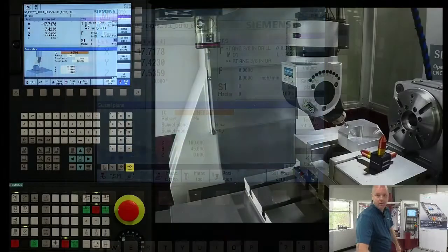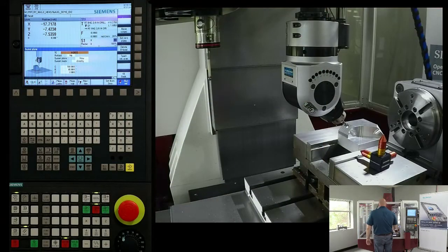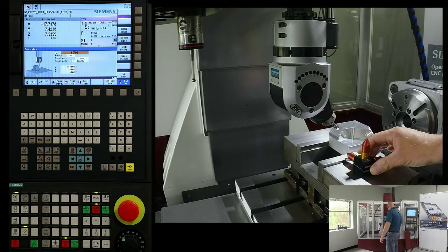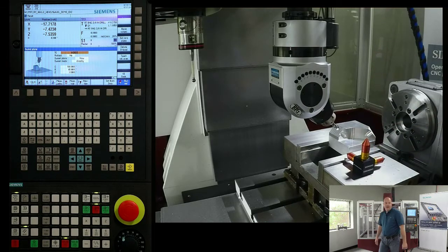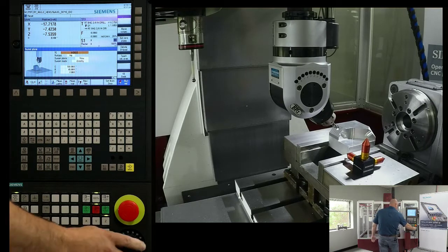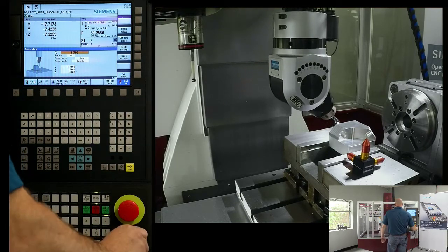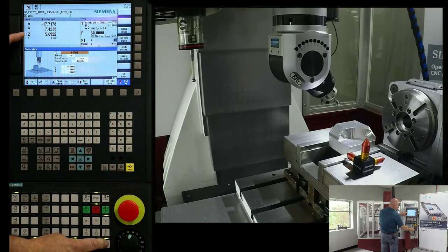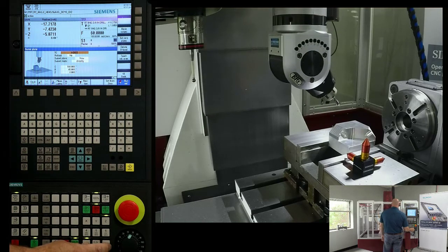So here you see an interior shot of my machine tool. Normally our coordinate system, like you see on my little cube here, is pointed straight up at the Z-axis orientation. So if I was to jog the machine right now, and we'll bring her up, you see how the Z itself, as I'm jogging Z, or if you can see on the display as I see the Z is moving, I'm moving normal to the machine spindle.